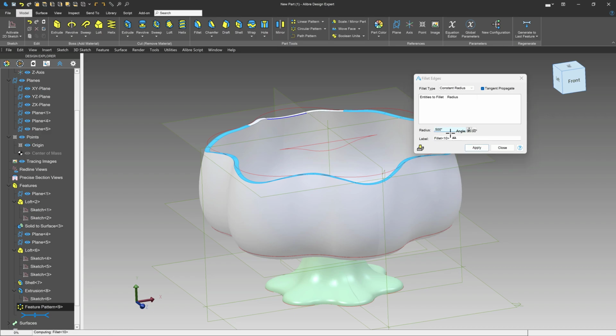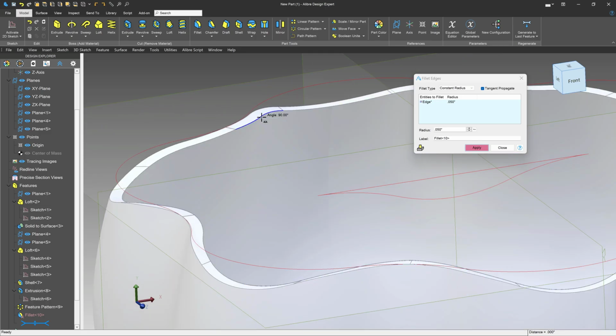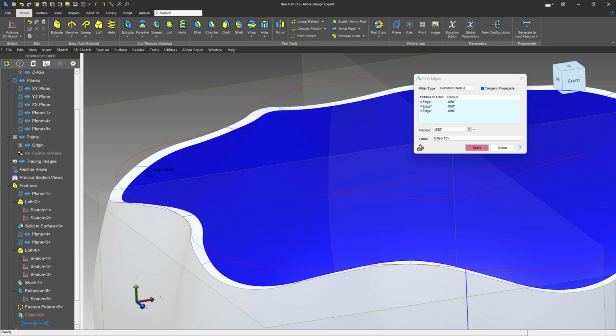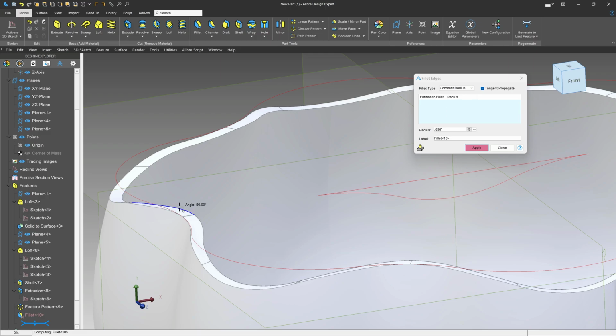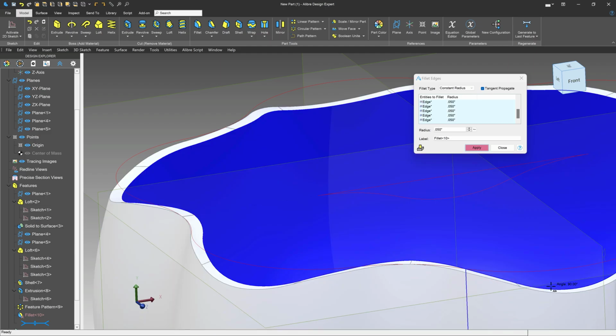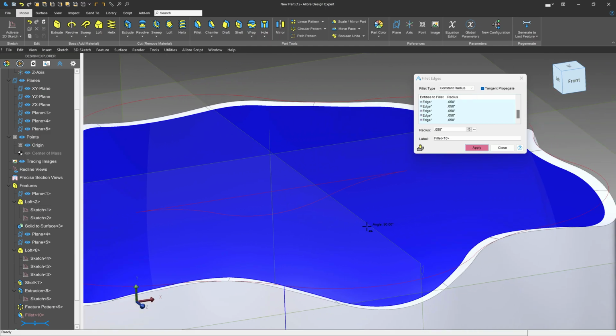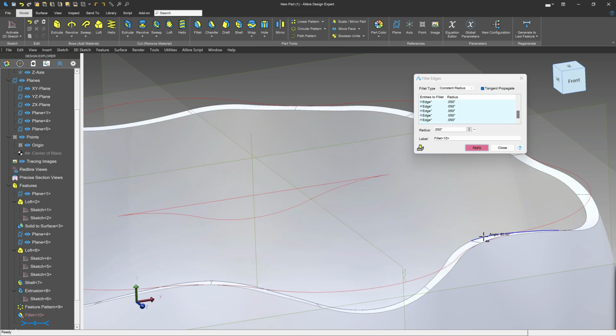And obviously 0.5 is pretty large. And Alibre actually figured that out, which I think is pretty impressive. But we'll reduce that to 0.05. You'll notice of course it didn't work, but we'll want to keep selecting some edges, and we're just communicating the continuity of what we want our fillets to be. So if you have a fillet that doesn't quite work, don't give up. Just keep telling Alibre how you want the continuity to be, and I bet something will catch on, especially if you're going through kind of a complex array of cuts like what we have here.